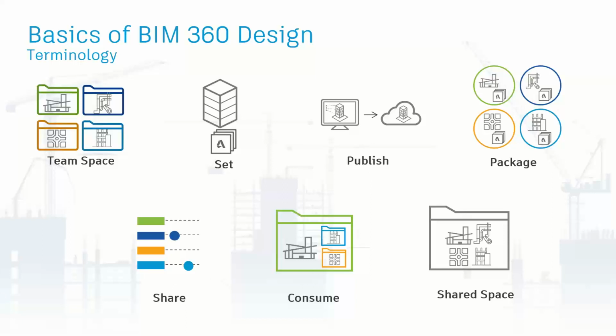What is consume? Consume means that you are bringing a copy of the other trade or discipline model to your own team space. So if I am the architect, I can consume a package that was shared by the structural engineer without having access to their central model. It's just a copy. And at the end, we keep an archive of all the models that have been shared in these packages. Everyone working in the project has access to this shared space, but it's just an archive of all the versions that are in these packages.